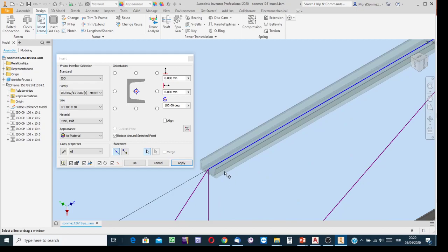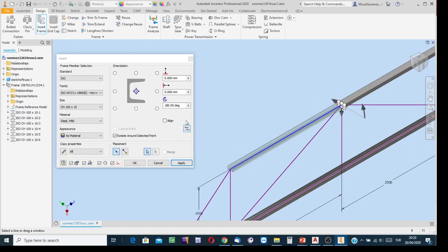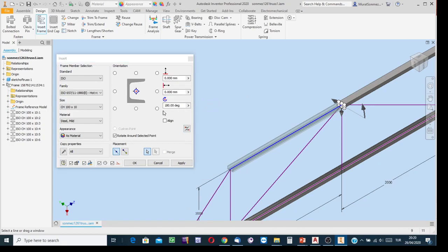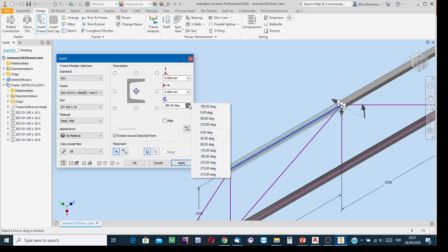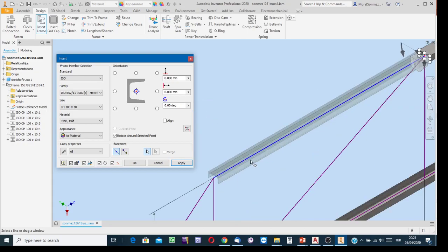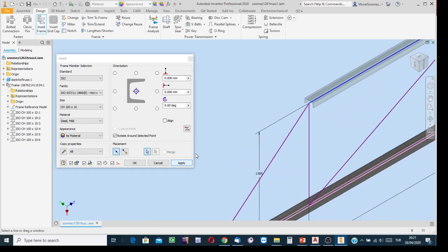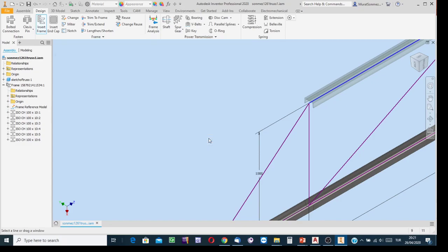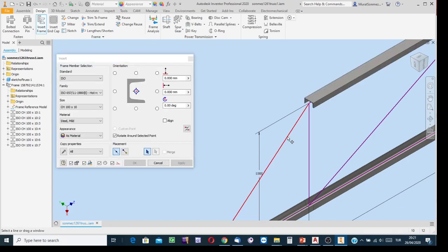And then check the legs. No, unfortunately, the legs are wrong. So rotate it. Well, in that case, since I said 180 and found it wrongly oriented, I know I should select 0 degrees. Okay, and now it is in the correct orientation. I don't want to take a risk for the next, so I say apply. You see, it is not so time consuming. 2 extra clicks are needed if you don't want to take a risk for each. Apply and OK. And then continue, indicate this one.